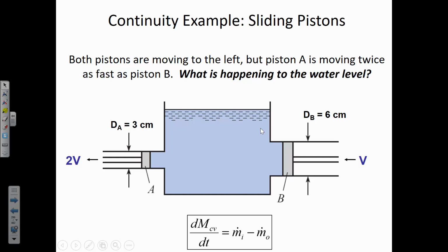All right, so why is it not staying the same? Why is the water level not staying the same? Diameter squared. Yeah. So remember, I set this up specifically to make it look appealing, to make it seem like, oh, in equals out. So the trick is that here the diameter at B is 6, but the diameter at A is 3. So it seems like, oh, well, that has double the diameter, but this has double the speed.